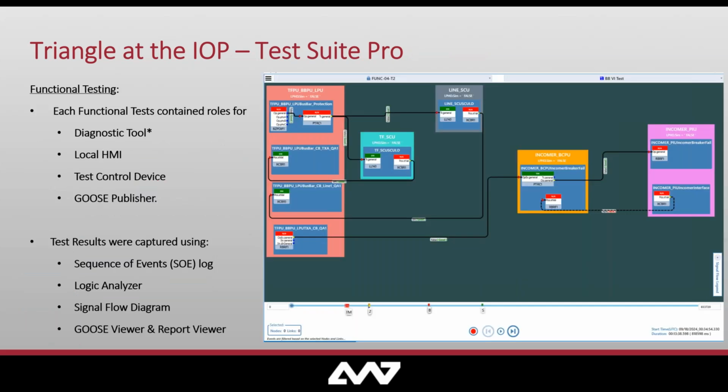Sure. Okay, so I'm going to go ahead and pivot back to Test Suite Pro, but talk about how it fit into functional testing. So I have defined several roles. These included roles for devices like Christoph talked about earlier, so the BCU or the SCU, the LPU, the different IEDs that were protecting or controlling different pieces of the substation. It also defined roles for tools. So these included diagnostic or monitoring tools, local HMI, test device control, and even Goose Publisher.